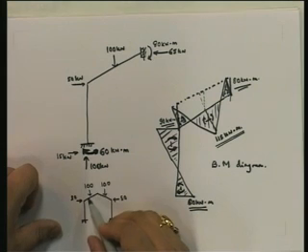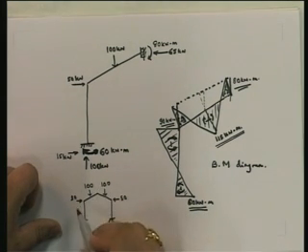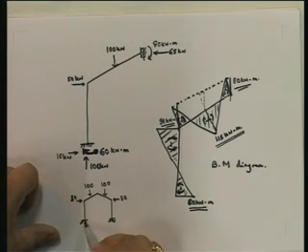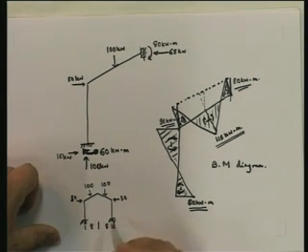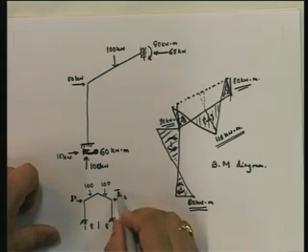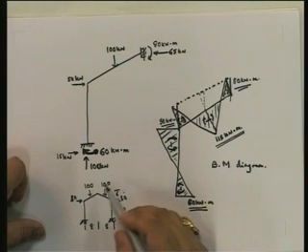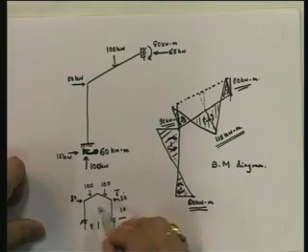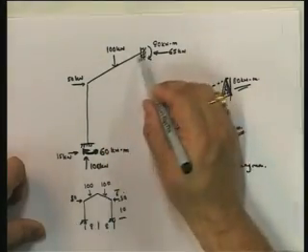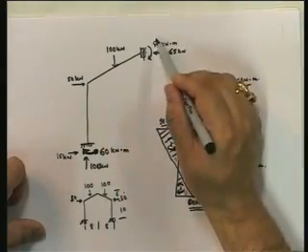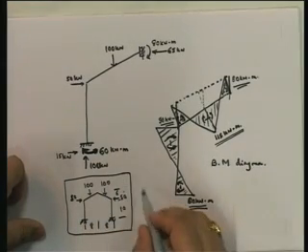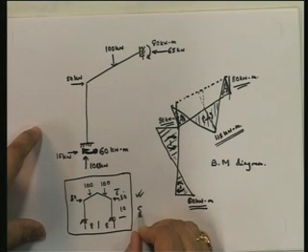This portal frame problem has vertical loads of 100, uniformly distributed, and equal and opposite lateral loads of 50-50. Here this would be 8, 8, this would be 10 and this would be 6. This is a portal frame, and by using symmetry it can be simplified to this particular problem. So the problem that I am solving, although it does not look like a real problem, is actually a very real problem. This is a solution to this problem using symmetry.